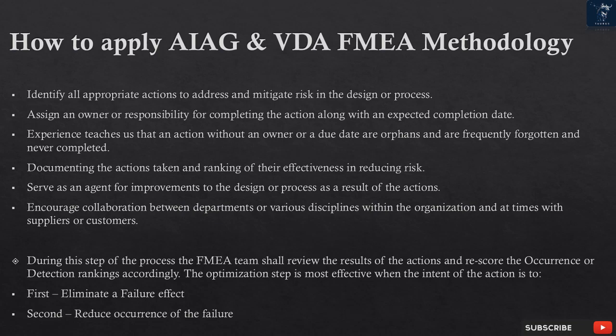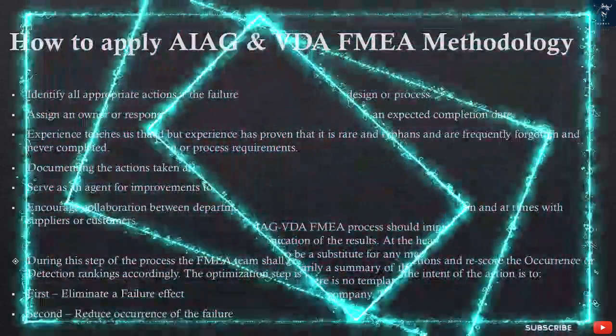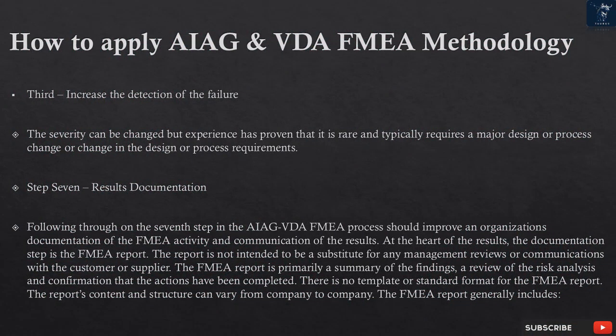or detection rankings accordingly. The optimization step is most effective when the intent of the action is to: first, eliminate a failure effect. Second, reduce occurrence of the failure. Third, increase the detection of the failure.